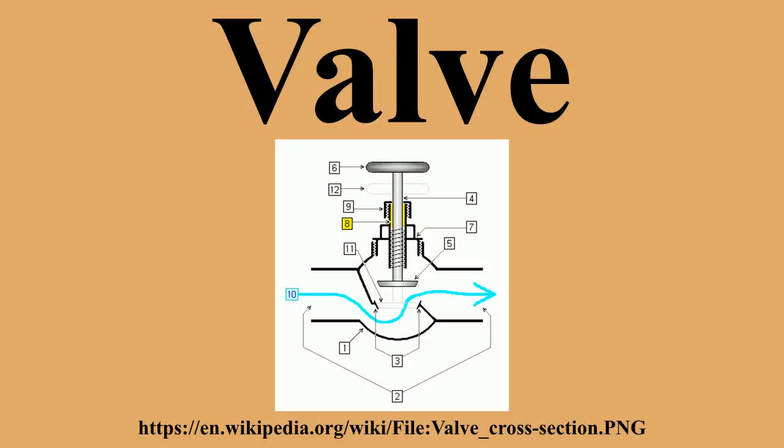The valve stem can be threaded such that the stem can be screwed into or out of the valve by turning it in one direction or the other, thus moving the disc back or forth inside the body. Packing is often used between the stem and the bonnet to maintain a seal. Some valves have no external control and do not need a stem, as in most check valves.